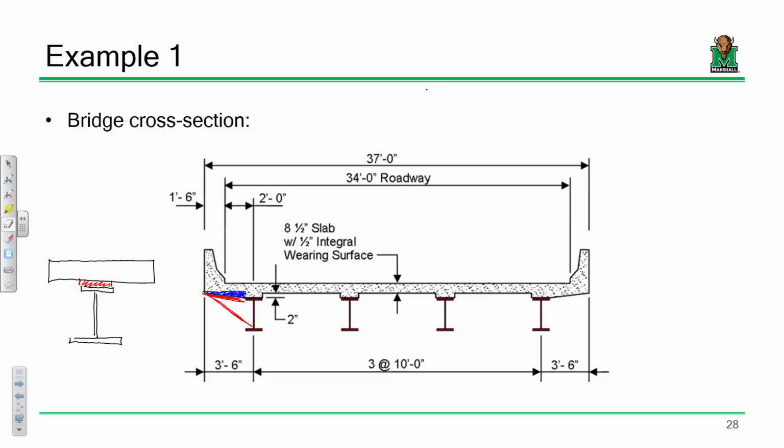So then your girder would need to support all that weight? You're exactly right. Because think, if I have a bridge and I just pour wet concrete, how is it resisting that load? How is it helping with the strength? It's just a puddle of wet concrete. It's just load at that point. Once it cures and becomes locked with the shear studs, it becomes composite, then it can help. Does that make sense? Everyone okay with that?